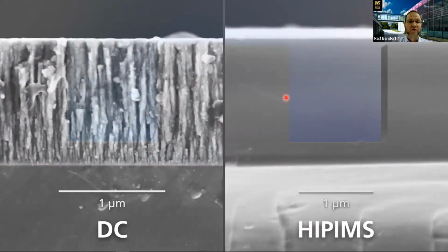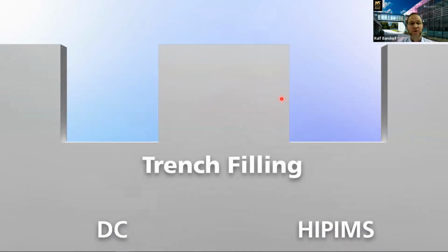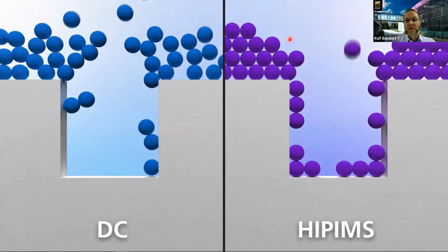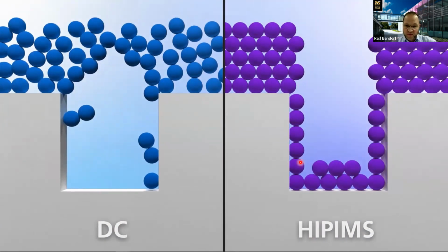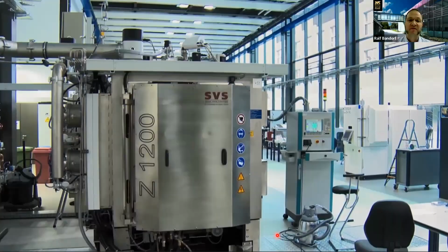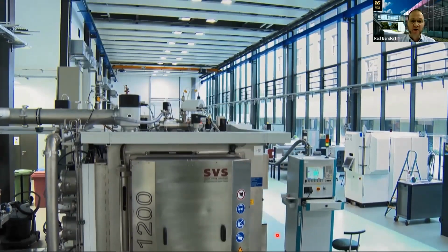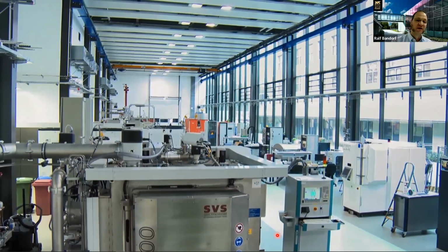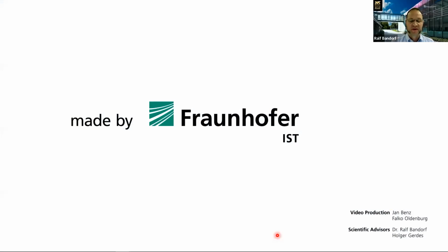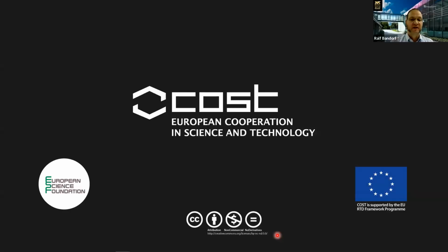That's an example for a nichrome coating. Or if you go to even very fine structures, you can coat the walls and side walls of very tiny features. Here, that's something with a diameter in the range of a few hundred nanometers and a micron in depth, can be even higher. And today, you have a lot of sputtering machines. So this is just a view in one of our coating labs, where you have today those processes in industrial production.